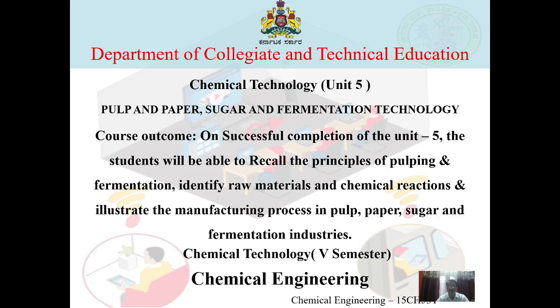The sulfur dioxide thus obtained is cooled quickly in horizontal or vertical pond coolers, and then it is reacted with calcium carbonate, magnesium carbonate and ammonia to produce calcium bisulfite, magnesium bisulfite and ammonium bisulfite.